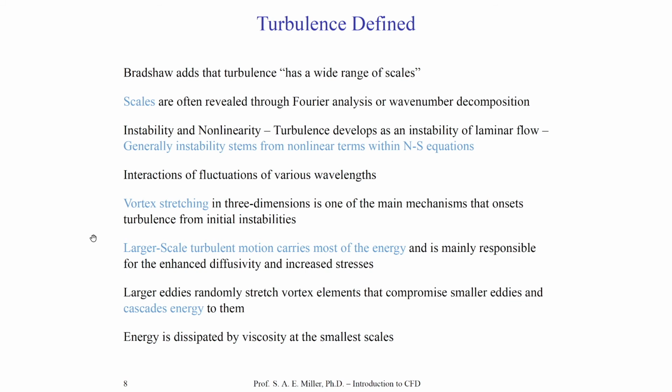And of course, it's interesting that since the large scales contain most of the energy, they would transport this energy through particular flows. For example, if you look at a turbulent jet, the very large-scale turbulent structures are carrying most of the energy. They're energetic and they're moving. The small-scale structures also contain energy, but much less. This can be shown mathematically and through measurement, through many different types of flows. It's something you should remember, and we'll see throughout our class.